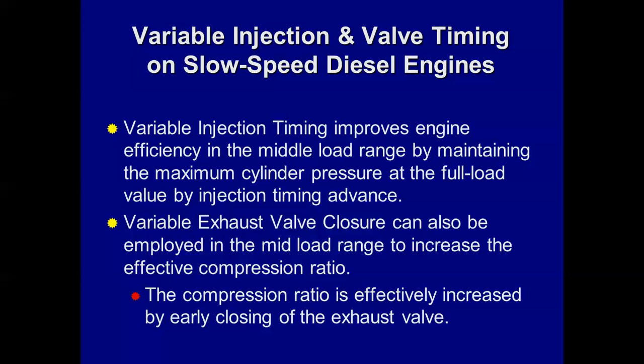You have a lot of valve overlap, or you're using a large portion of the air to cool the cylinder when you're at full load, right? So the exhaust valve will stay open past bottom dead center to allow that scavenging air to go through the ports and out the exhaust valve to cool the cylinder.